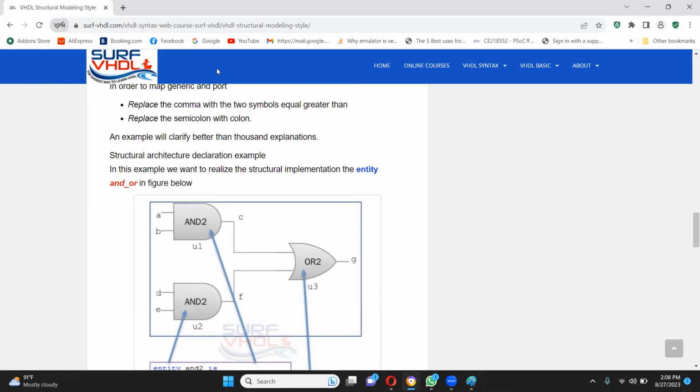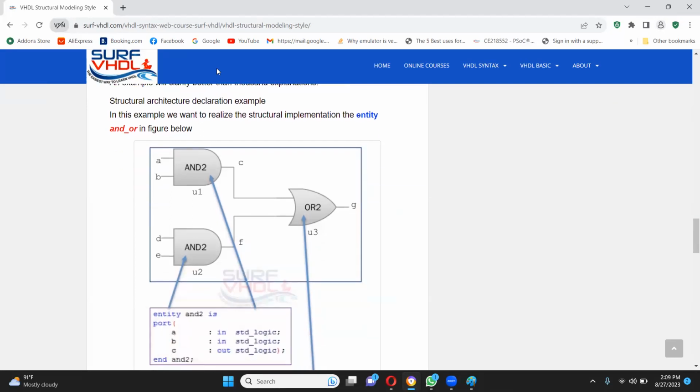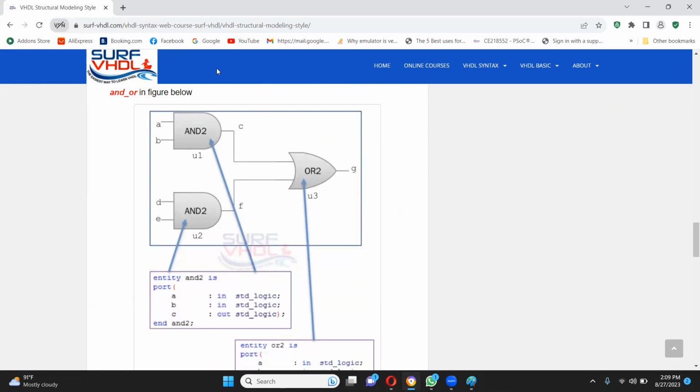Can you tell me the difference between a combinational circuit and a sequential circuit? So basically, a combinational circuit consists of logic gates whose output at any time is determined only from the present combination of input, and they have no memory. Right. The other way is a sequential circuit. Perfect. So where you start from here is you see the circuit first and see how many AND gates and OR gates there are. There are two AND gates and one OR gate in this circuit, and the AND gates are of the same type, two-input AND gate with one output.